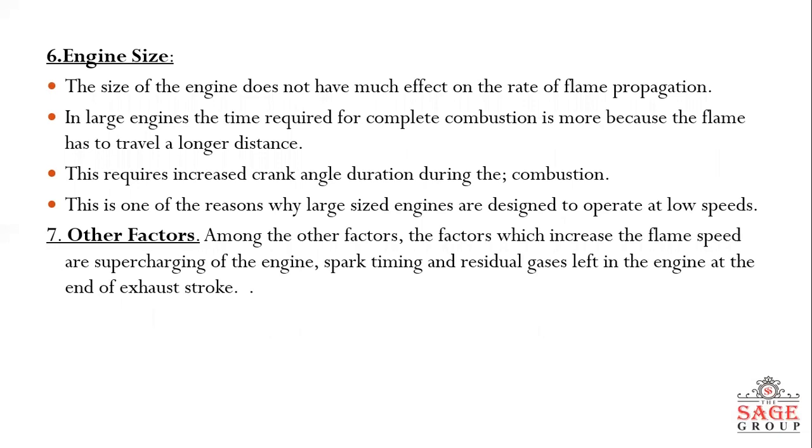Then we have engine size. The size of engine does not have much effect on the rate of flame propagation, but in case of large engines, the time required for complete combustion is more, since the flame has to travel a longer distance. This requires increasing the crank angle duration during the combustion. This is one of the reasons why the large size engines are designed to operate at low speed.